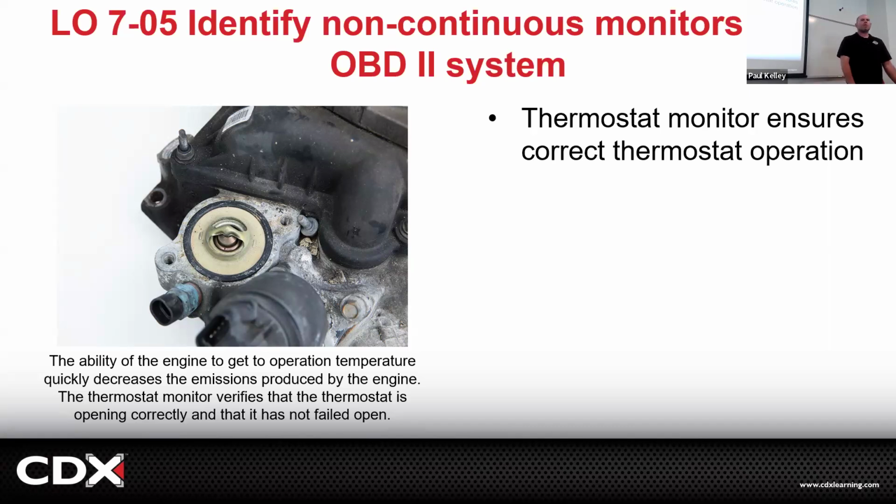Yeah, we monitor that. P0128, engine coolant below thermostat regulating temperature. If your thermostat's out, your PCM is looking at your coolant temperature sensor and watching how quickly it heats up. And if it doesn't heat up quick enough, boom, you get that code, P0128. Fail smog, you're polluting more than 1.5 times the emissions level it was certified for.